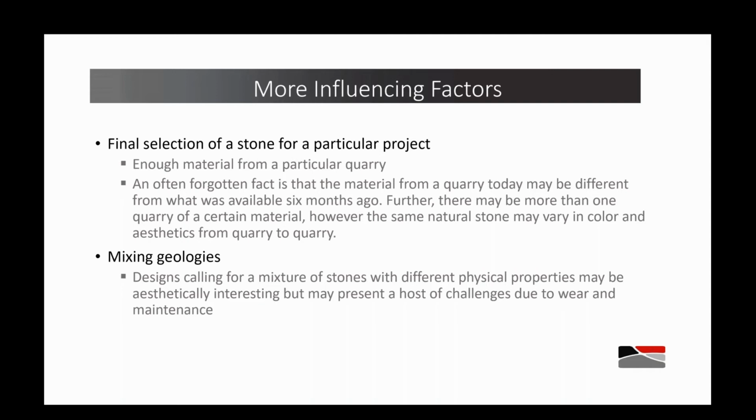And then also be careful when you're mixing stones. Sometimes you can't find the exact stone that you want, but a blend of 2 or 3 stones will give you the look that you're striving for. Just be aware when you're mixing stones with different physical properties, that they're going to weather in a similar fashion, so that one stone doesn't start to look significantly different to the others over time.